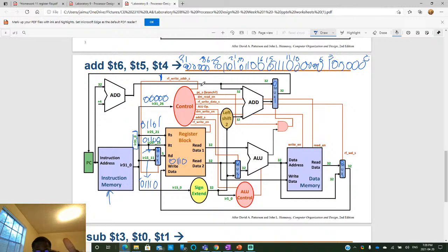And that abbreviation, if that's what I'm going to call it, means register file write address select. So basically, what it's saying is we are writing some data into the register block. Hence, the select line should be a 1. Okay, so this would be a 1. So remember, we're just walking through how the processor executes this instruction.